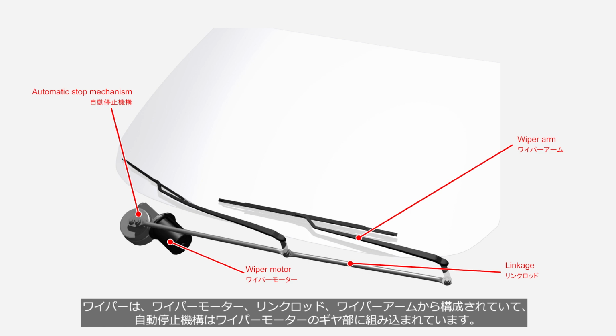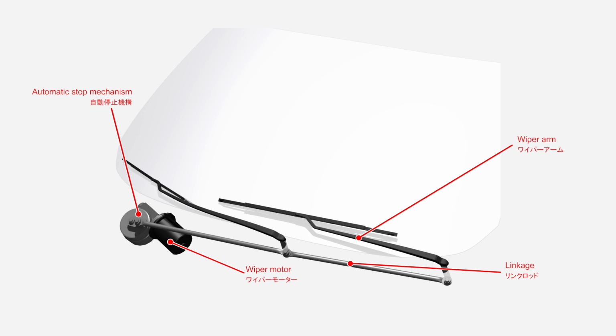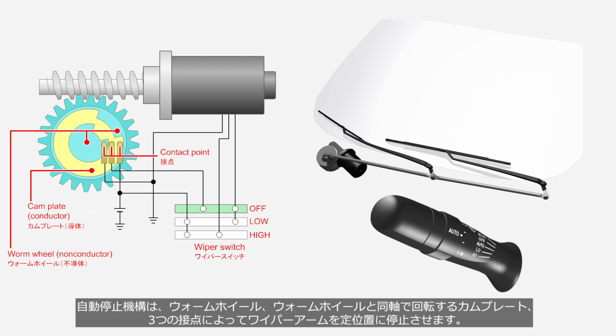Wiper systems consist of a wiper motor, linkage, and wiper arms. The automatic stop mechanism is integrated into the gear assembly of the wiper motor. The automatic stop mechanism consists of a worm wheel, a cam plate that rotates coaxially with the worm wheel, and 3 contact points. They bring the wiper arm to the home position.